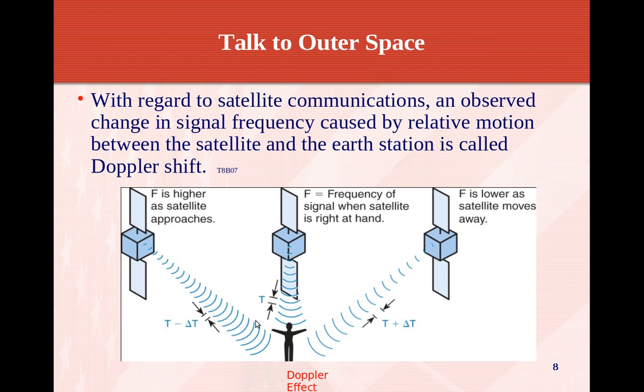And you're going to constantly have to tune your radio as the satellite passes. If you do this stuff by hand, it's a combination of adjusting your antenna and adjusting the frequency, and you do this all in concert. It's kind of an interesting thing to do, and it requires a little bit of practice.